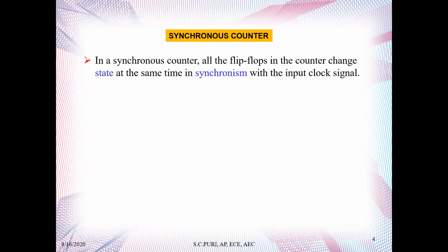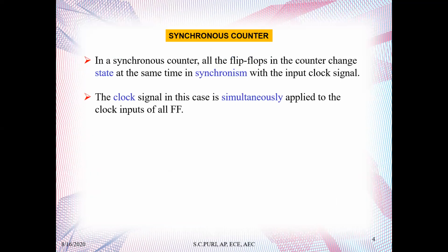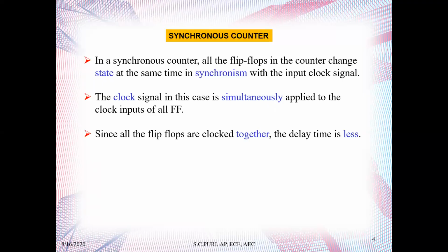Let's now talk of the synchronous counter. In a synchronous counter, all the flip-flops in the counter change state at the same time, in synchronism with the clock input signal. That means they are synchronized with the same clock. The clock signal is simultaneously applied to the clock inputs of all flip-flops. Since all the flip-flops are clocked together, the delay time is less.